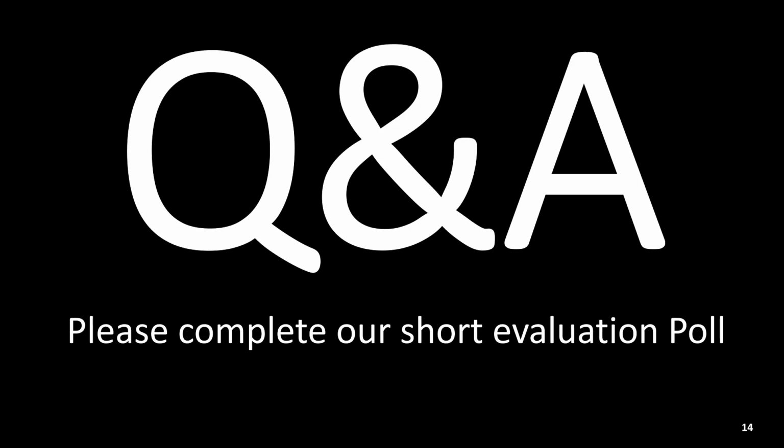We do have a question. Wonderful. Do you count for T's, elbows, and other fittings in the ground loop? That's from Steve. Well, you do by converting it to equivalent length. So instead of actual linear feet of pipe, you do want to add a certain footage in for elbows, T's, fittings, and generally there's not a lot of fittings in the ground loop supply and return. So you don't have to bump the actual footage very much.